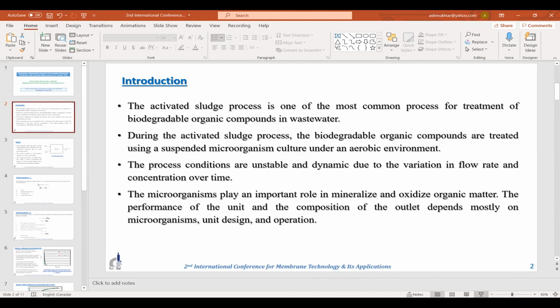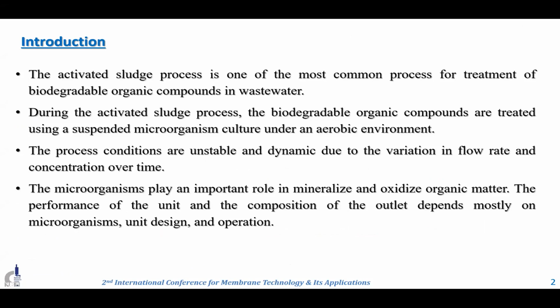Sorry, let me maximize. So the team designed an activated sludge process for this industrial unit. One of the major problems that we had is that the activated sludge process is a dynamic process, especially in the startup period, until we reach steady state, where there are lots of variables and lots of changes taking place. So we came up with a solution for this problem: to develop a model to study the dynamic behavior of the system, the expectations, and the optimum parameters that can lead to a short startup period, as we will see here through the model.